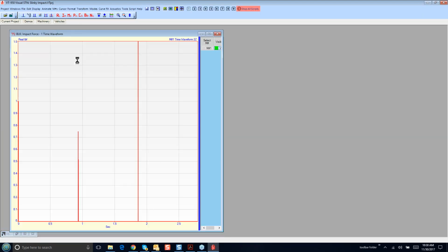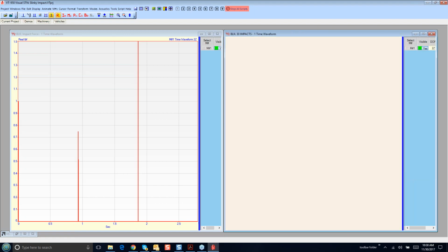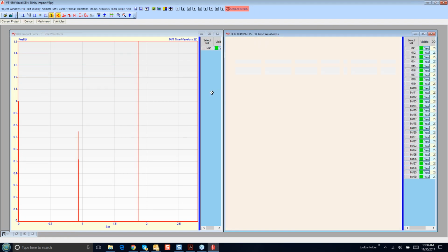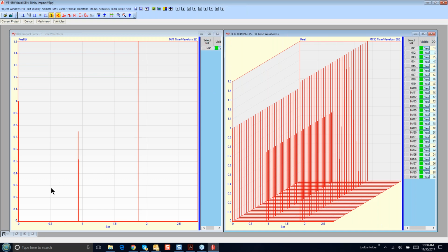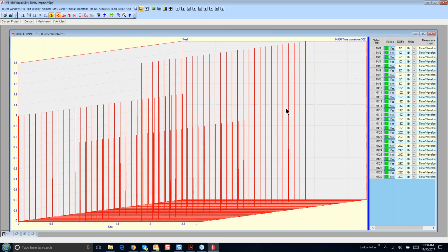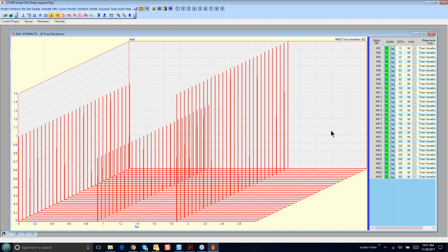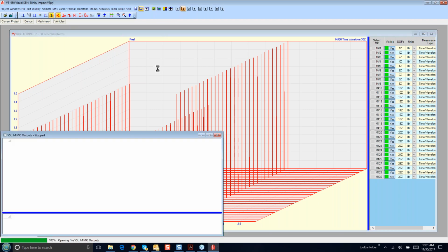And let's go ahead and look at a simulated Slinky impact test. So here are some impacts in a window, and what we're going to do is build a whole data block full of impact signals. You can see there are actually 3 of them here, and we're going to do some averaging of the data. What I've done with this first hotkey is basically fill up a data block with the same impact signal, except there are 3 of them. And we're going to use MEscope to first take these impacts and compute the response of the flat plate to the impacts. Then we're going to post-process the impact and the response in an acquisition window as if we're simulating a real impact test.